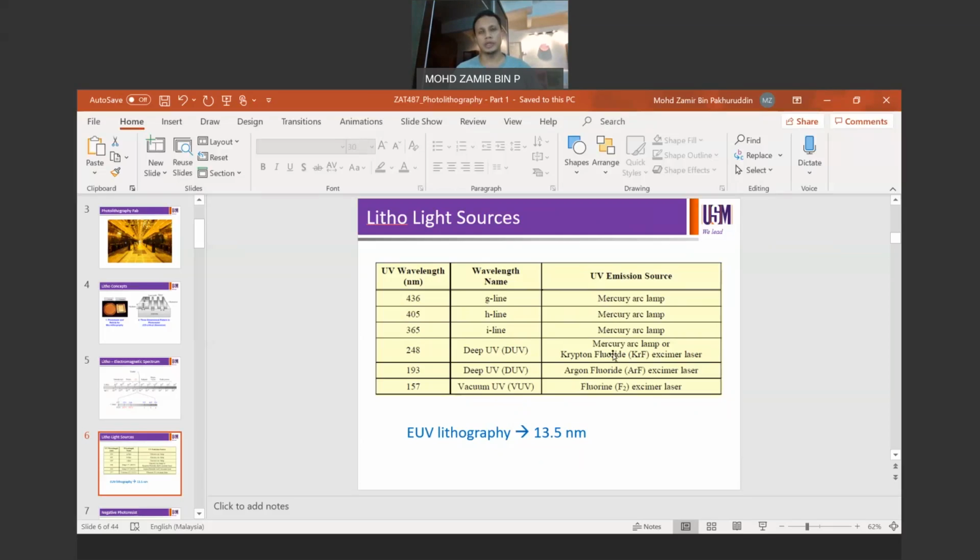If you want to go below 200, for example a 200 nanometer feature CD on the silicon, you need to move your illumination system from I line to deep UV. With deep UV at 248 nanometer as your illumination wavelength, you can print down with good resolution on the silicon with a feature CD of somewhere around 120 nanometer. If you want to go below and below, you then have to move to a more advanced lithography system.